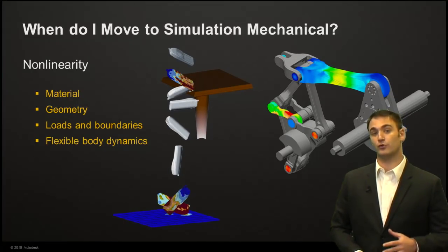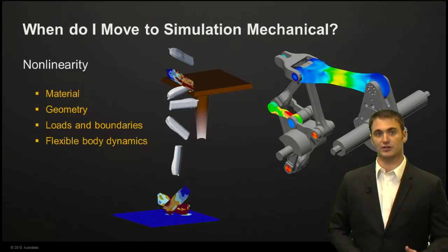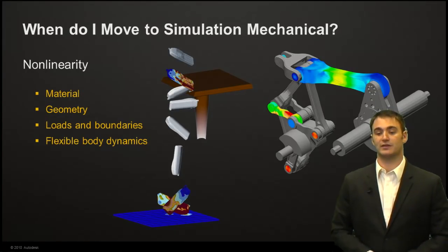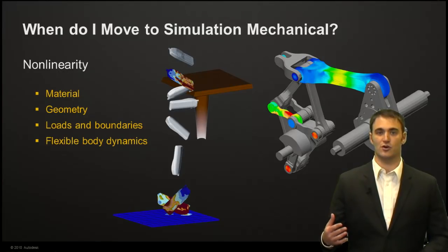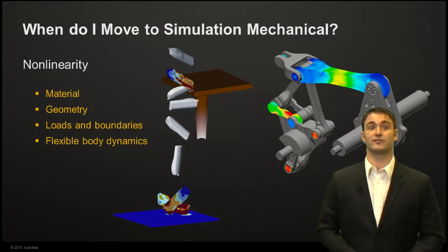You can also do full dynamics. Since this is a fully momentum integrated nonlinear solver, it's going to let you take a look at different speeds. So with something happening over a second versus over a minute, it may have different stresses resulting from that.